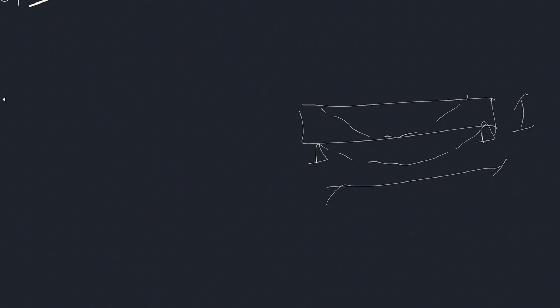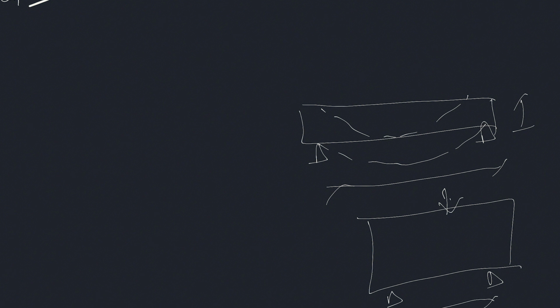But if this ratio is really short, imagine having a very deep beam and your span is quite short but is carrying a significant load. In this case, your span to depth ratio is quite small and your beam is not really going to exhibit flexural behavior, in the sense that it's going to be bending. Instead, the structure, especially the concrete, is going to redistribute the stresses internally through compression and tension in the element. And this is what is usually solved using strut type models.